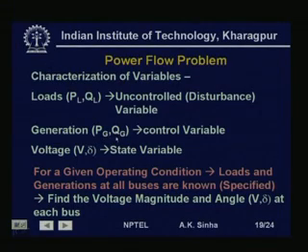So, he adjusts the generation at various bus bars so that he gets an optimal performance, and therefore, these generation variables PG, QG are our control variables, whereas the voltage magnitude and angle at all the bus bars, which basically relates these control variables as well as disturbance variables in the system, is the state variable of the system.